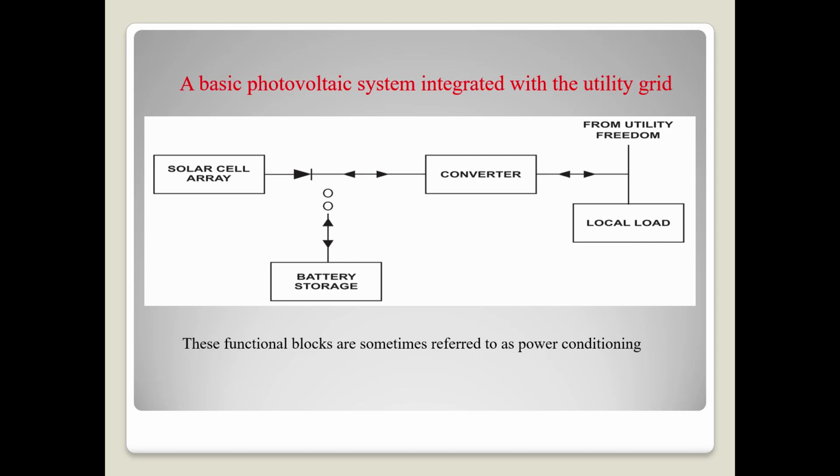The energy should flow only into the load. Now, what is a load? The power consumption devices that we use in the household, we say as load. The stored energy from the sun's radiation should be delivered only to the load, and there should not be any reverse flow. So it is done by means of this diode. This diode we say as a blocking diode.